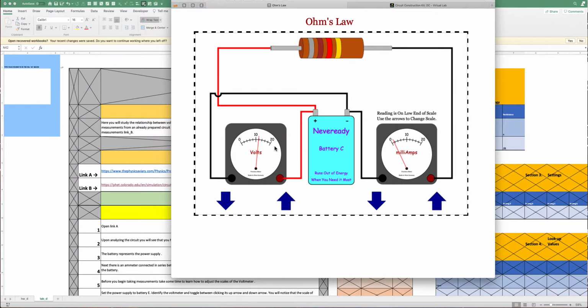And the same thing is going to apply for the voltage. So here, for this voltage, let's look at it on two different scales. Let's pick another battery. Okay, so let's pick this one. Let's look at it on this scale. On this scale here, the voltage reads 2.5 volts, and let's go to this scale. Here, it looks like it's a different reading, but if you notice, it's 1, 2, 3, 4, 5. So here this is 1, 2, 2.5. So they both read 2.5.